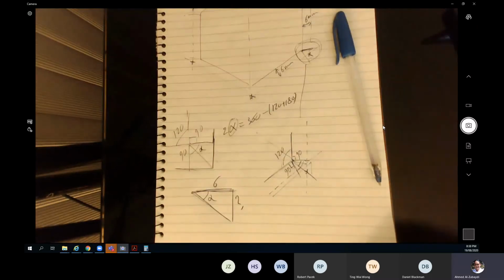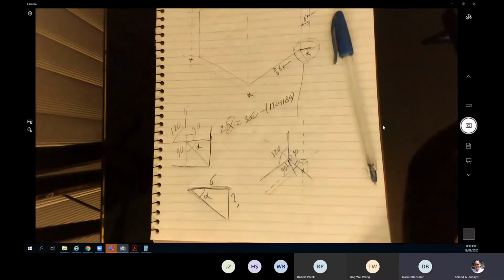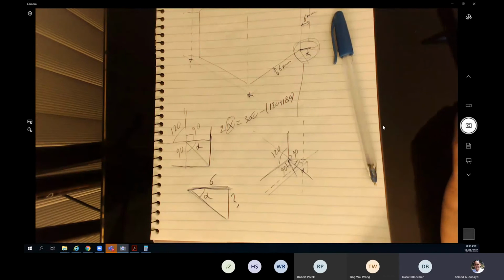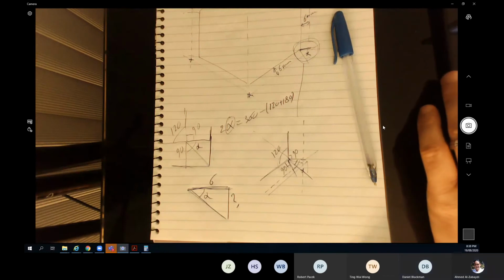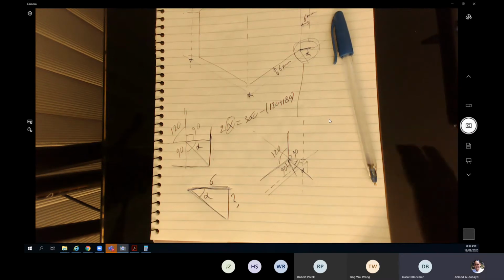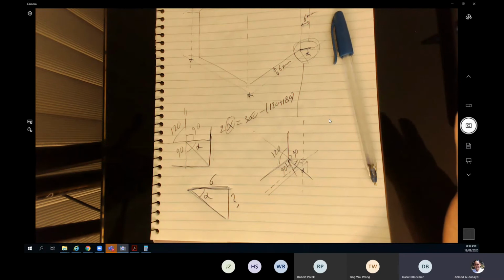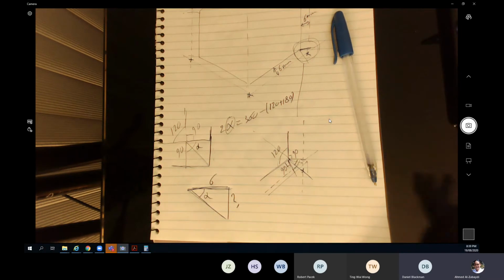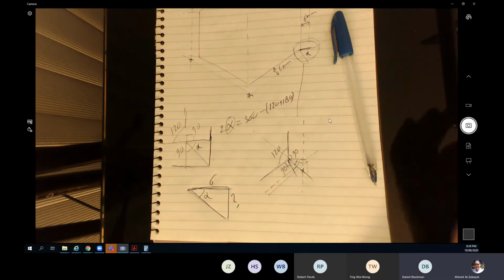Okay, done. That's all we need to do for the G-code part. Just a question about the depth that you go down to. Do you just go a little bit beyond the depth when you're face milling, or do you go exactly? No, we left it as it is because that's what we meant to go. We just left the pad for the production for the table. We don't want to cut the table if a mistake happens.